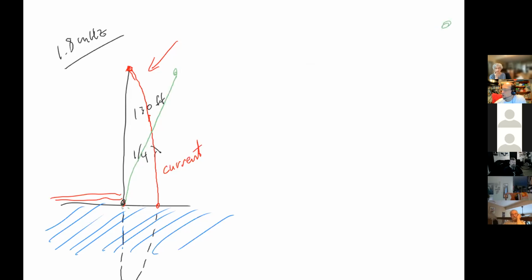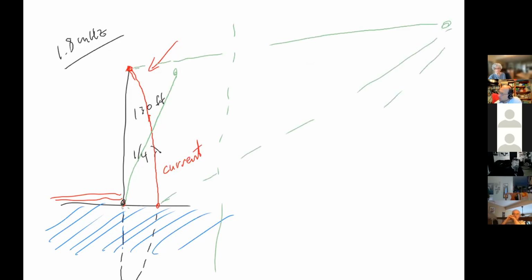If I didn't know that there was a ground plane there, I just saw an antenna right there, I would see an end with no current, and I see a center point with peak, and down here, what would I see? If I didn't know that was a reflective surface, it would have to be 0. Well, I'd see another end of the antenna, wouldn't I?